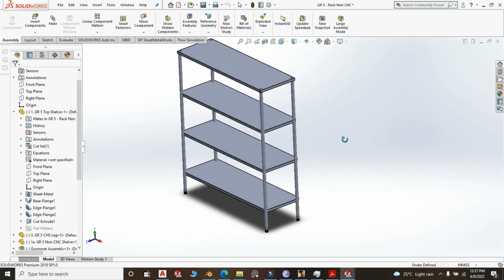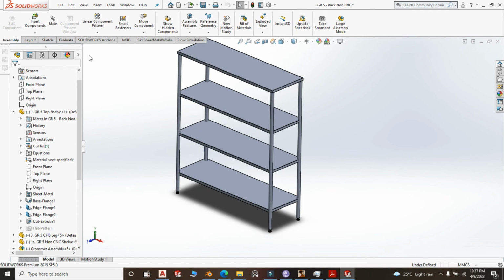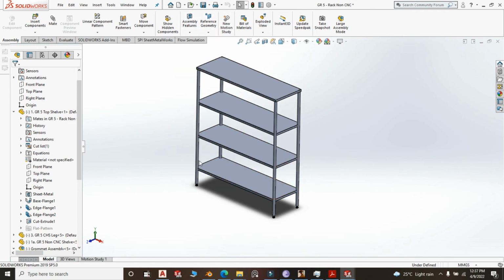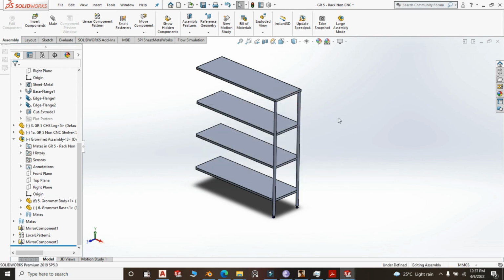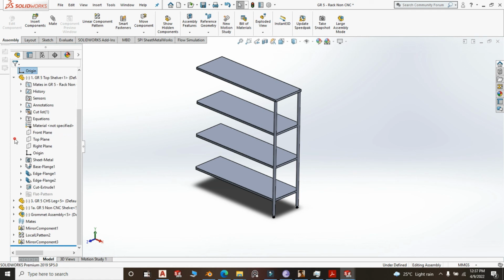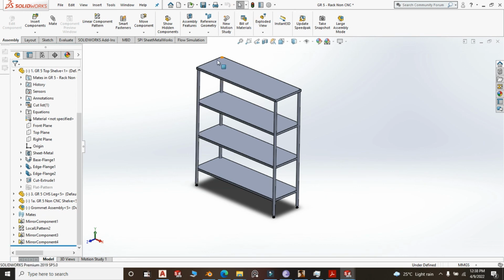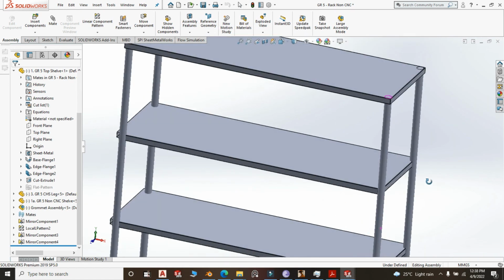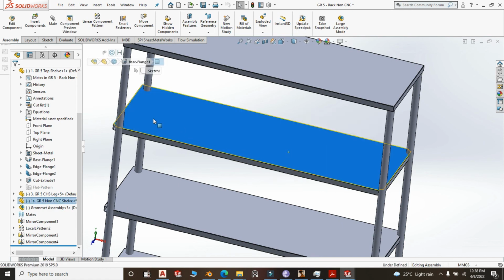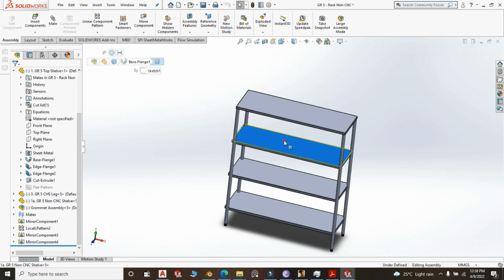I'm wondering, no, we shouldn't have mirrored them on the top plane, so let us undo this. Let us delete mirror 4. You can edit the plane. Can I choose which one? You realize something? The mirror plane is okay, the size of this rack is the one which is not okay. You should reduce this by 38. Let's see, open.